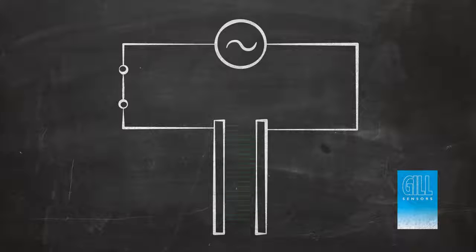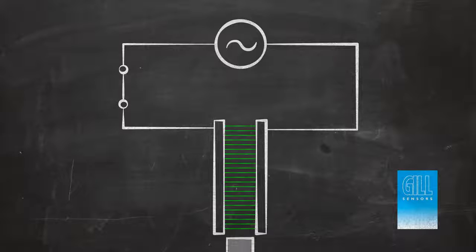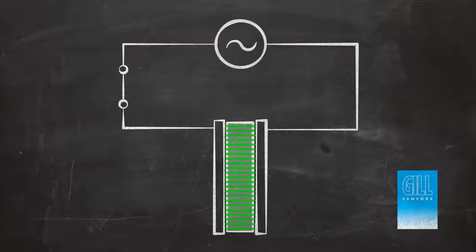Capacitors have the ability to store energy in an electric field between their electrodes, caused when a voltage, or potential, is applied to the circuit. The property of capacitance relates the amount of energy stored in this field to the applied potential. By placing non-conductive material between the electrodes, the ability for the capacitor to store energy increases, and so the capacitance increases. This material between the electrodes is referred to as the dielectric.